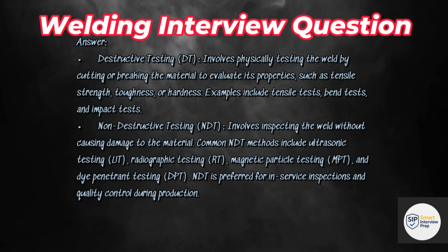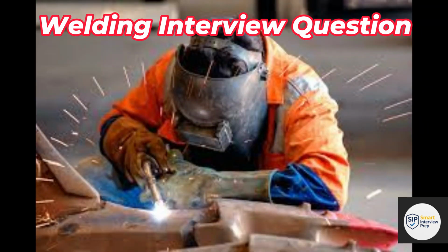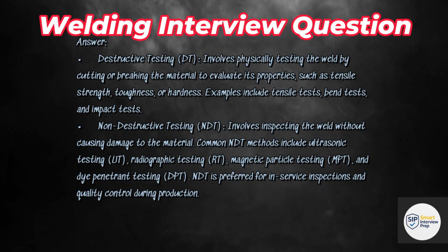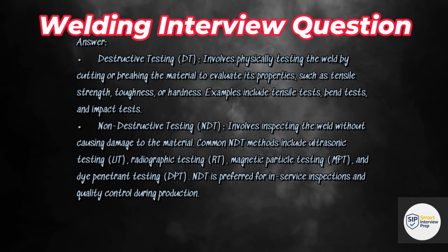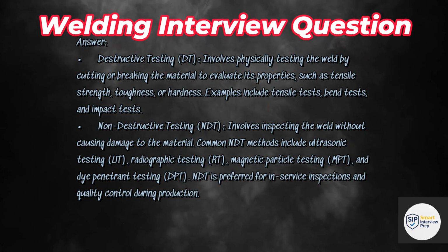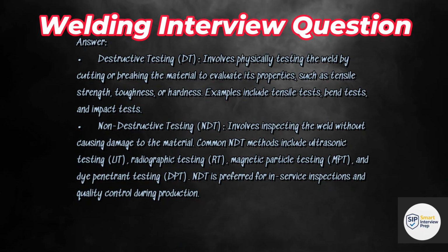Non-destructive testing, NDT, involves inspecting the weld without causing damage to the material. Common NDT methods include ultrasonic testing, UT, radiographic testing, RT, magnetic particle testing, MPT, and dye penetrant testing, DPT. NDT is preferred for in-service inspections and quality control during production.